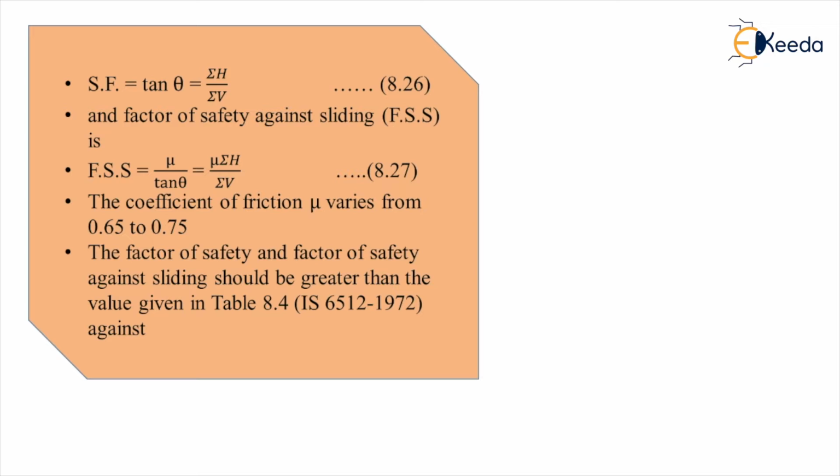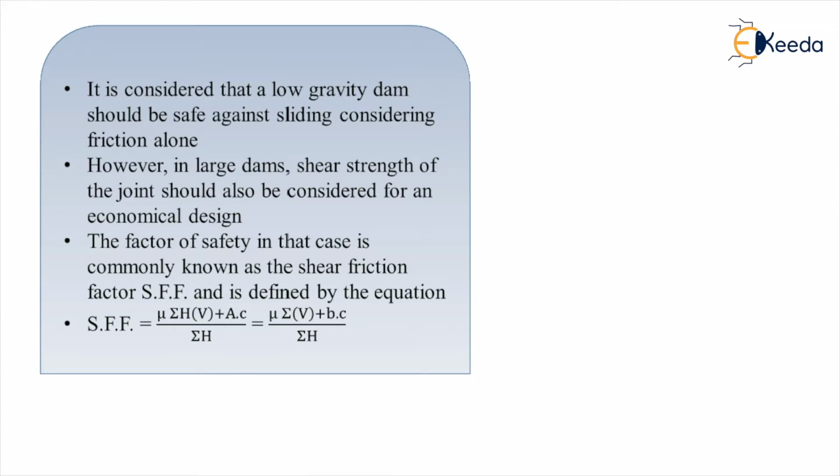And this value, the factor of safety against sliding, should be greater than the value shown in the table given by the IS code 6512-1972.